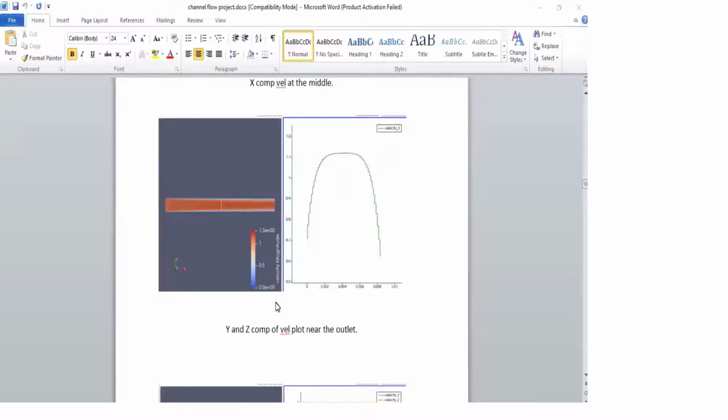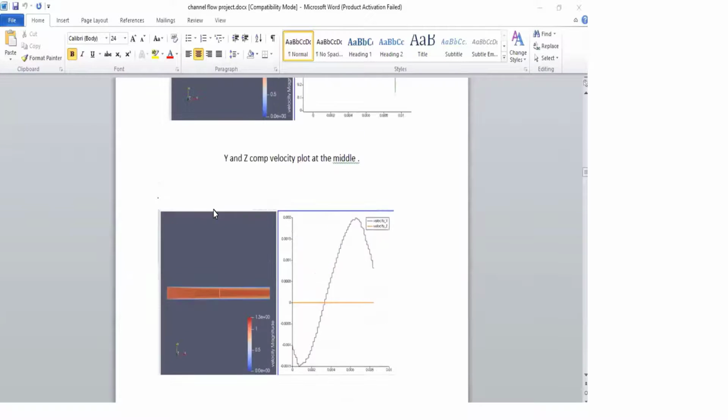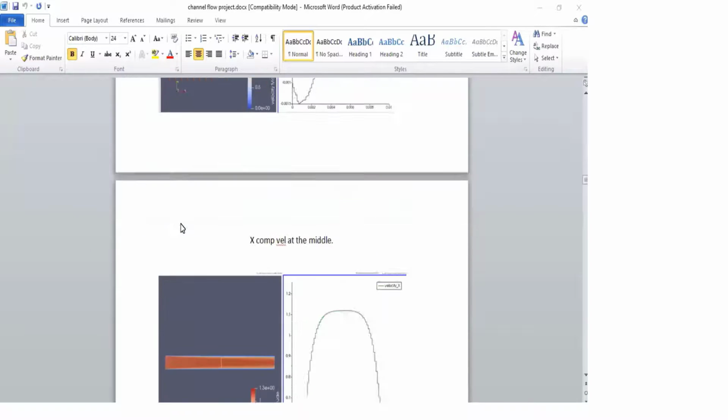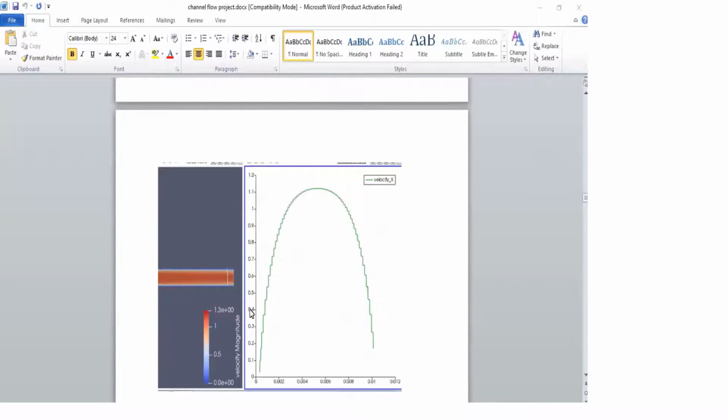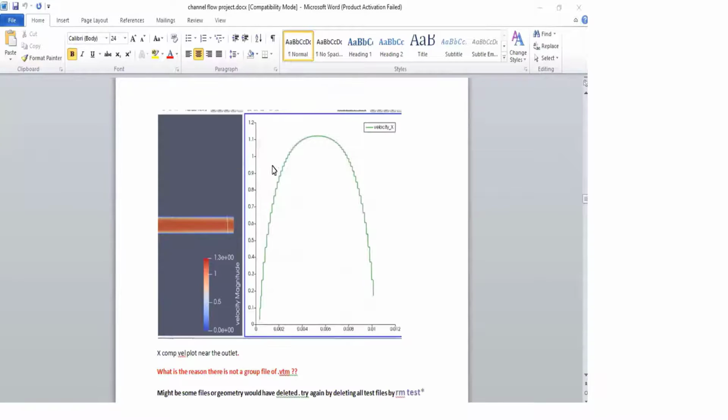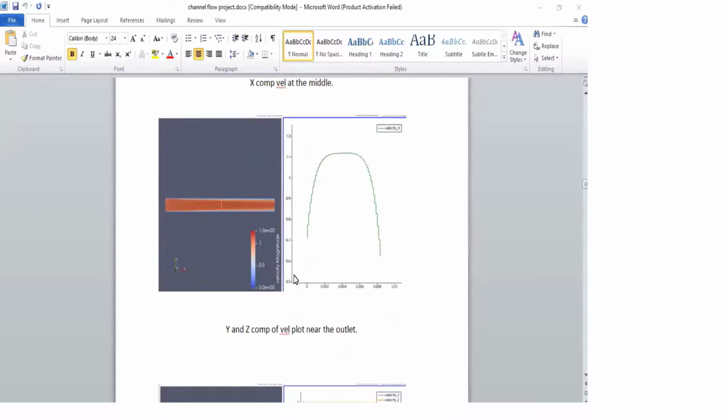As you told now, the velocity profile, this one, sir, x along y distance. But where did you check it? Means in the fully developed region, or exactly? You can check at any location. So I have created one at the middle of the center, I have here created at the extreme left, and in the below figures I have also created at the extreme right, correct? So here, if you see extreme right, I'm getting a very good parabola, compared to the middle one.